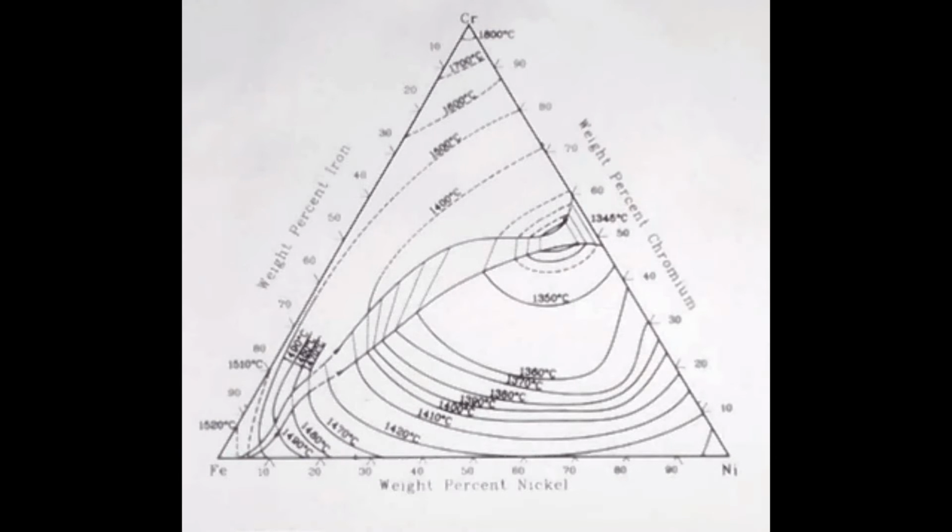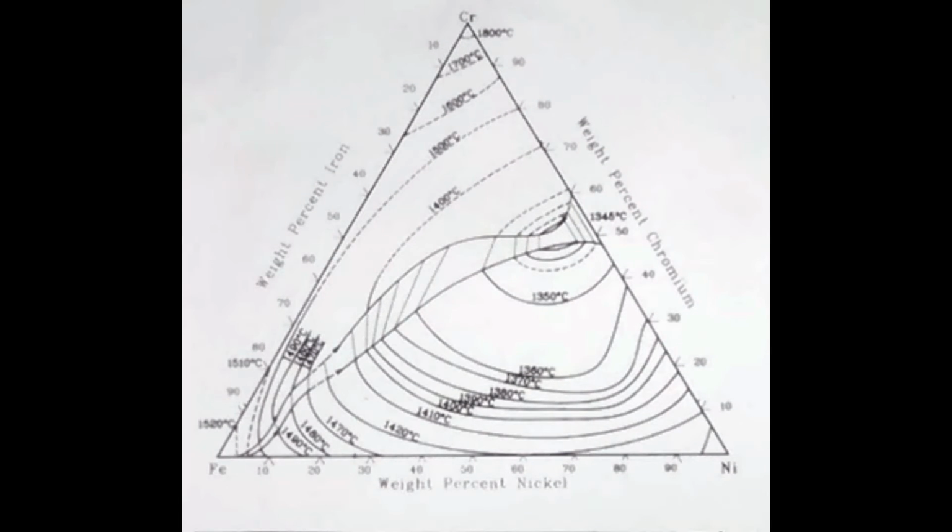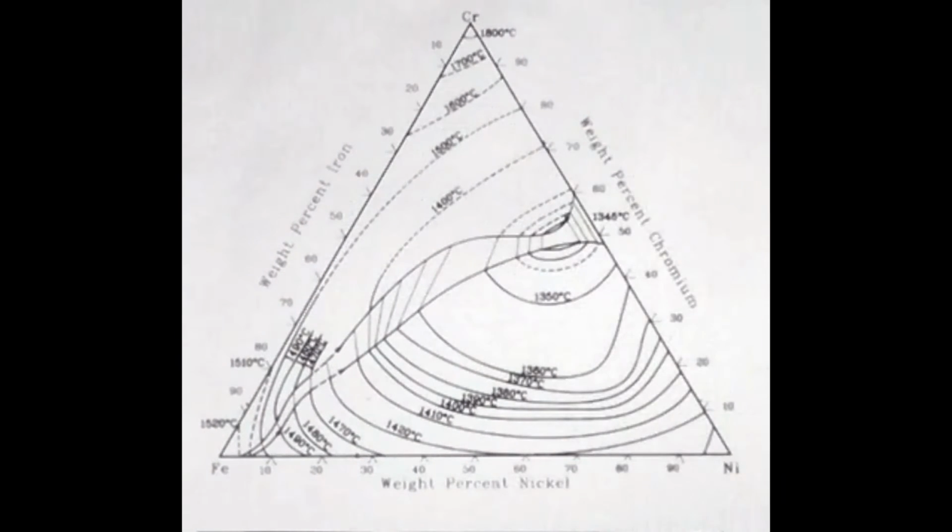To use the method of parallel lines approach, we would draw isocomposition lines parallel to the respective sides opposite of the triangle from each percentage of the component that we are working with. Our point of interest will be where all three lines intersect. This temperature is going to be the desired temperature in order to melt the steel. First, let's start with iron at 60%.